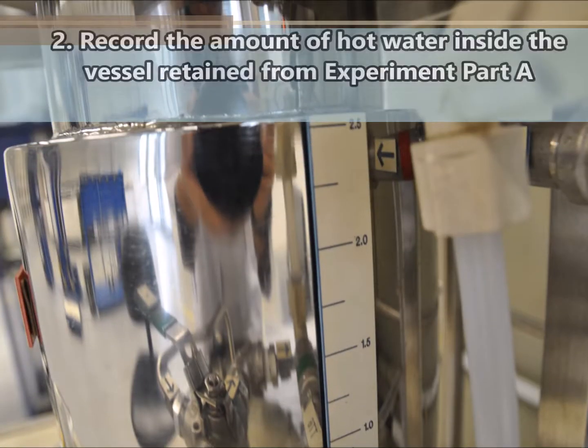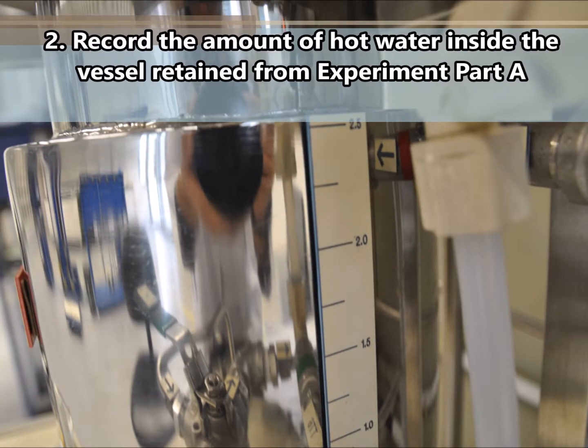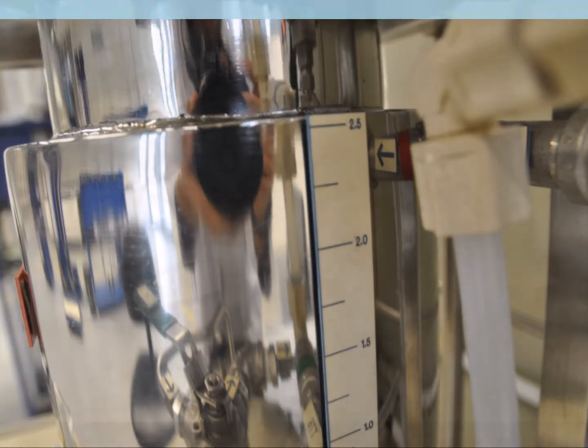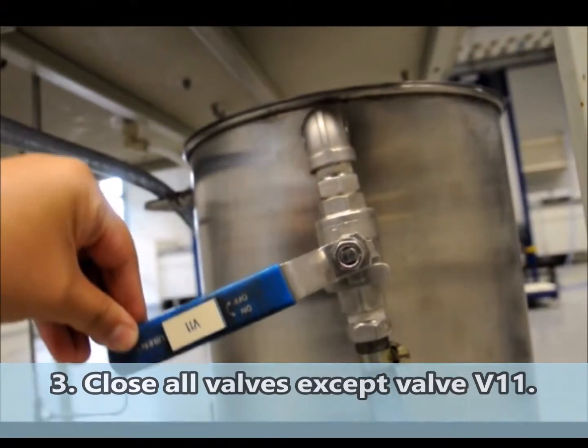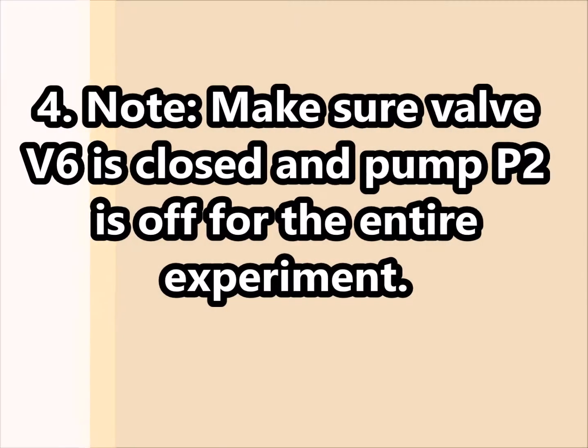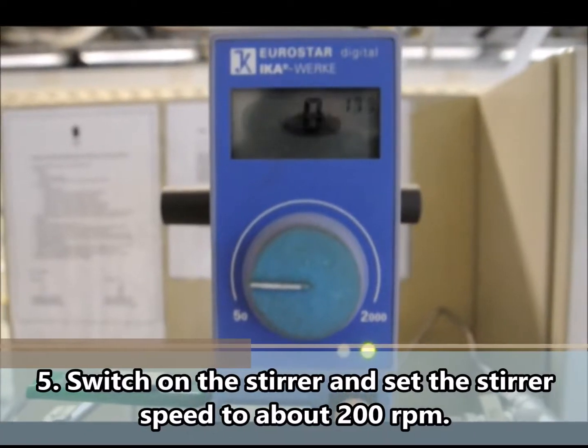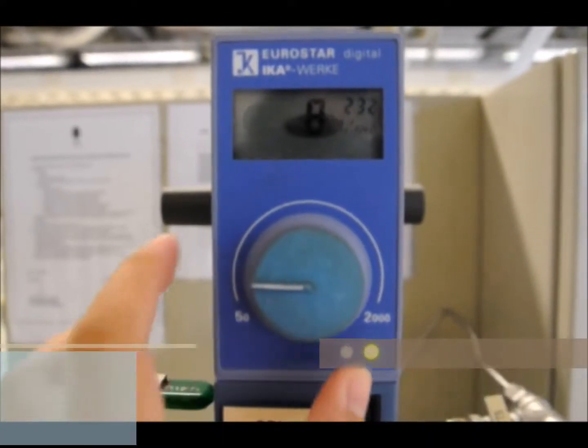Record the amount of hot water inside the vessel retained from Experiment Part A. Close all valves except valve V11. Make sure valve V6 is closed and pump P2 is off for the entire experiment. Switch on the stirrer and set the stirrer speed to about 200 rpm.